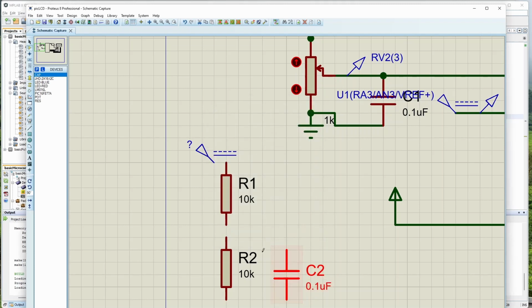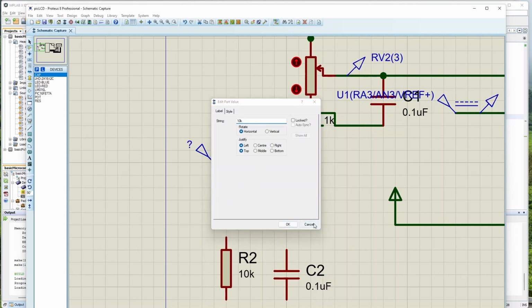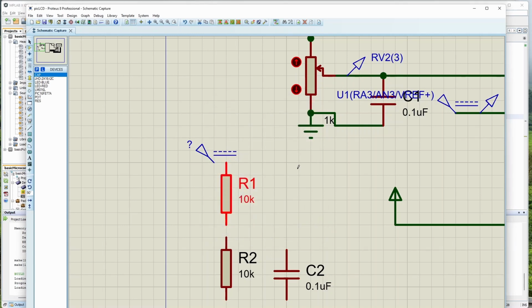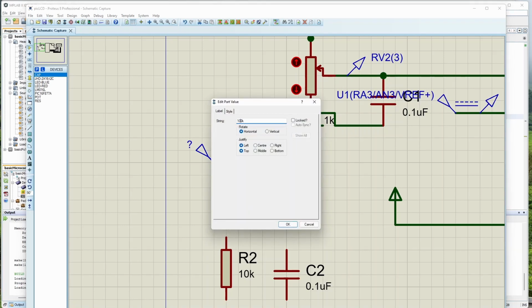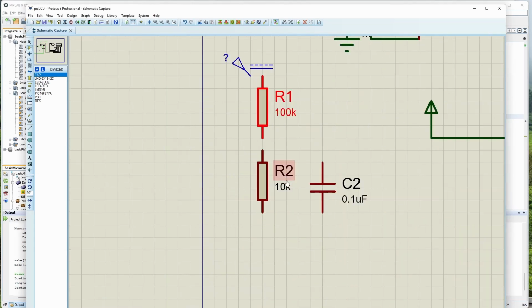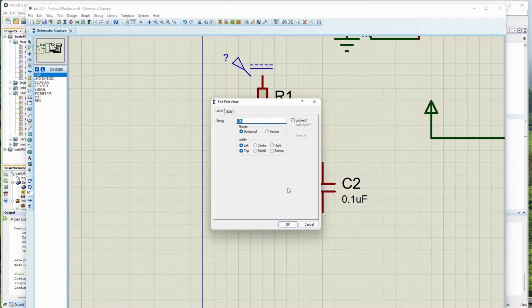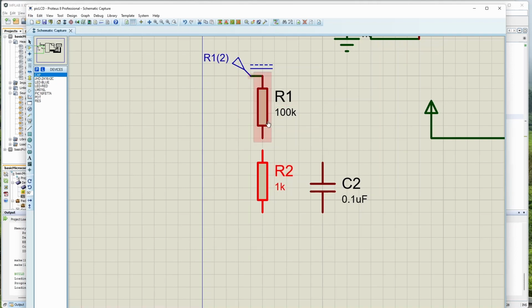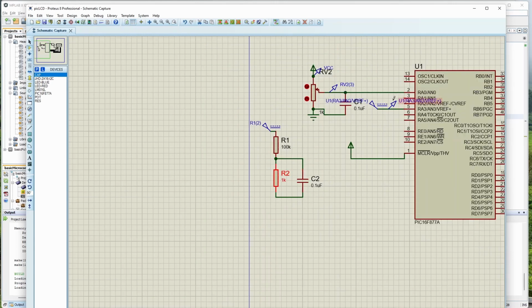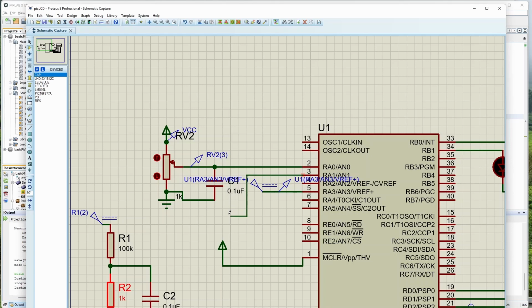Microfarad, and I have to step it down from 100 volts to 2.5 volts. So it's always better to use a very high value, so that the current dissipated in this resistance is very less. 100k, 10k, 10 times it will divide, I'll get 10 volts. I'll use 1k. And let me connect this to channel 2. For channel 0 we had used, let me use channel 1.